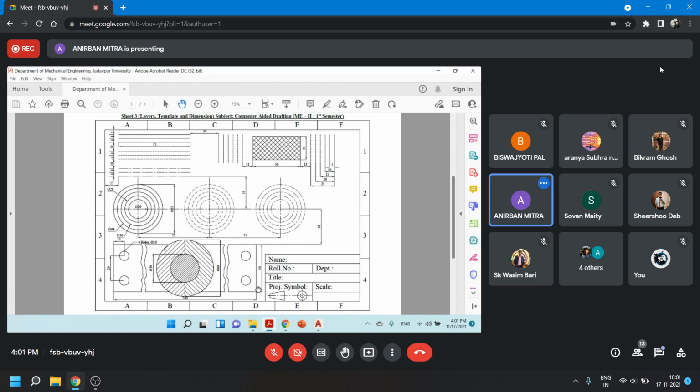The interesting object in this sheet is the bottommost one. You can see here that there are some broken lines provided. This total distance is 240, but with these broken sections. What it means is that within those two broken lines, there is a larger line, but it does not have any interesting part to it. It's simply a continuation of these two lines. There is nothing interesting happening within these broken areas. That's why this broken section is provided to reduce its size.